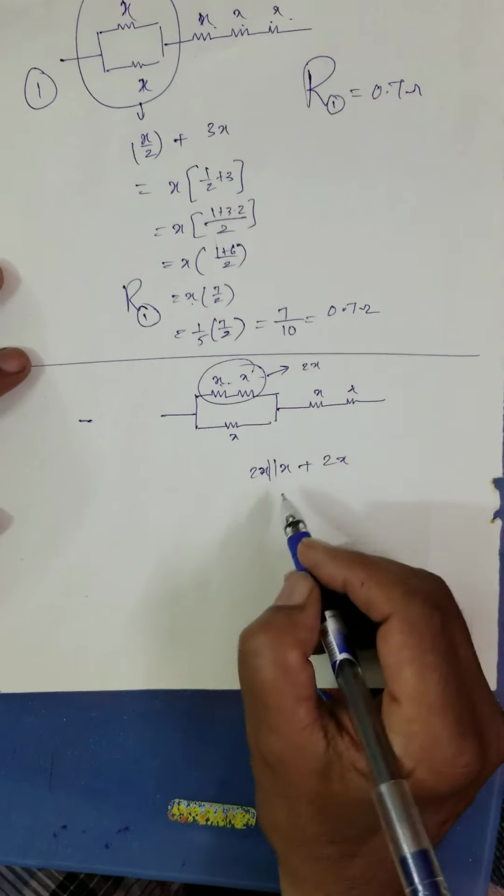See, potential difference is measured across any element that is called a resistor. Potential difference is measured in parallel. That means the voltmeter is the instrument which measures the potential difference. For a battery also, if I want to find the potential difference, I will connect a voltmeter parallel to the battery or a cell. If I want to find the terminal potential, I have to connect the voltmeter parallel to the resistor.